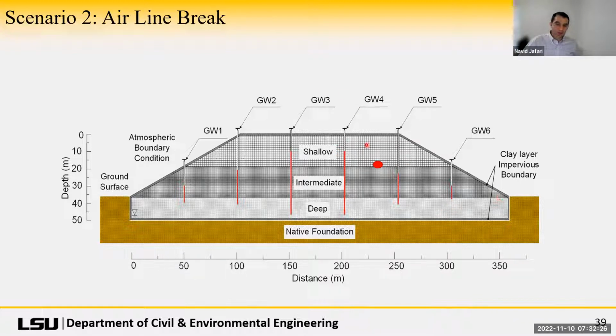They have pneumatic pumps in wells to remove the leachate. And so those pneumatic pumps then need air for them to work. And so for all of these gas wells, there are air lines going to them. And there are points where the landfill is growing and they put the next 20-foot lift, they raise the gas well riser pipes, but the air lines to those pumps are actually buried inside the landfill, and they can be buried about 20 feet or 30 feet, and those lines then just come up with the gas well.